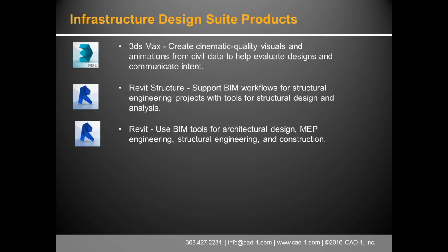Yeah, so Revit Structure is geared towards structures, right? We want to make sure that we have a column in here, and this column is a load-bearing column. Whereas Revit, in the general sense as architects would use it, they want to put a column there and they want it to look good. And they're going to put these facades on it. And they would create a wall that has these different materials within the wall, whereas Revit Structure would look at this as, it's a wall, is it a bearing wall or is it not a bearing wall? And what's the weight of it, so we can do analyses on it like that.